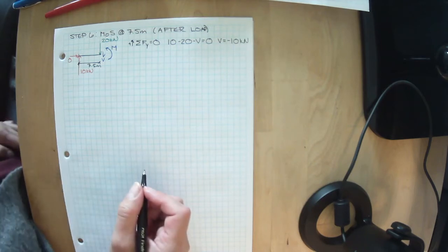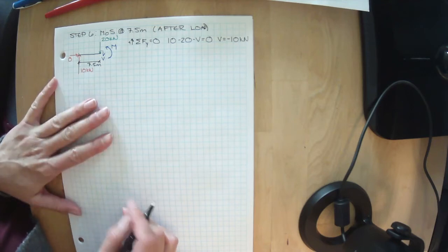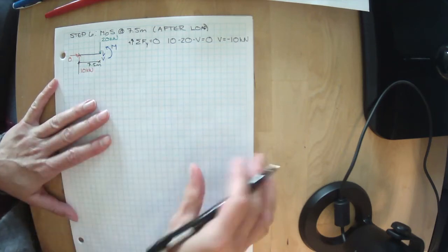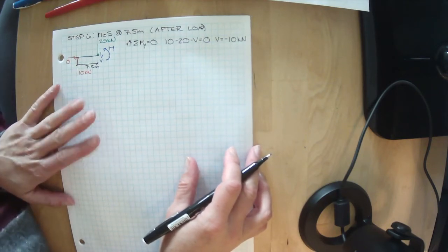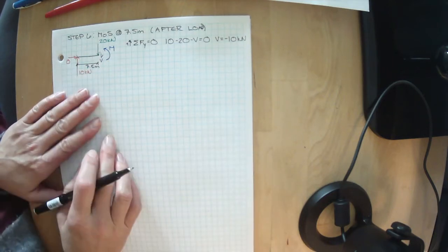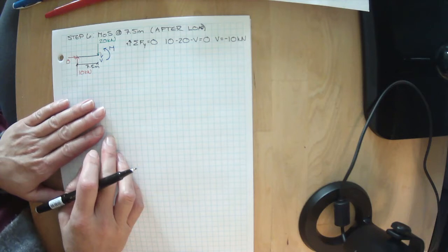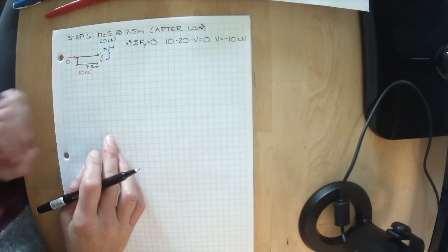Now, remember with axial, a negative meant that we had drawn our arrow wrong? Well, that means the same thing here. In axial forces, it was really important because it told us the difference between tension and compression. So this has told me I've drawn my arrow in the wrong direction, but the value of positive or negative shear is irrelevant. It doesn't have a meaning.